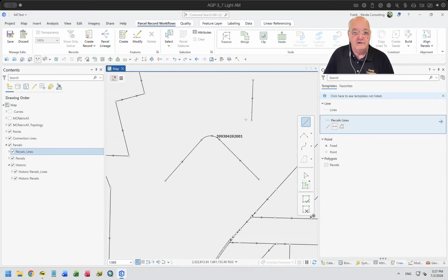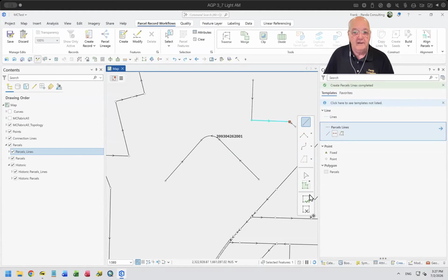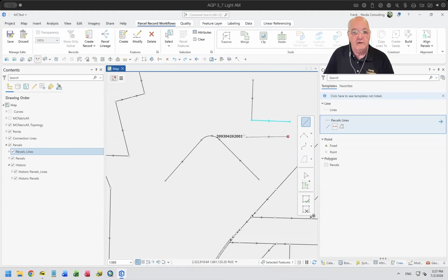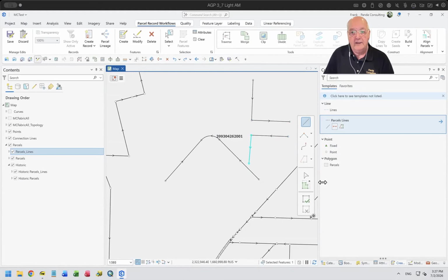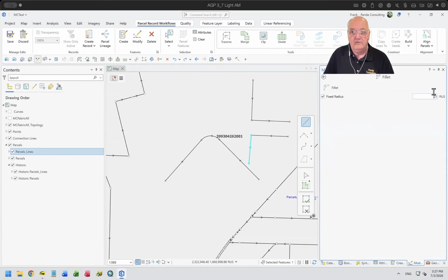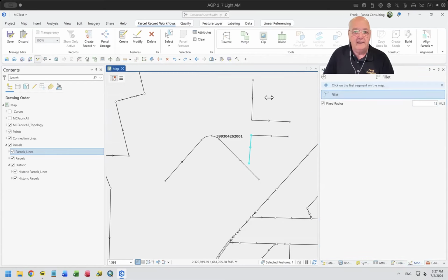We would have street center lines that we would create by paralleling off of, and then we would do a fillet and say that our curve cut maybe was a 15-foot radius, and we would go here to here, there, here to here, here. Again, it trims, fills everything up, puts the curve in there. It's a really nice tool.